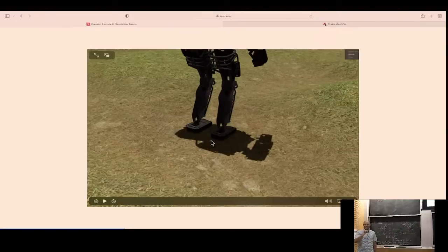It's the fingers. It turns out the way that we simulate the WSG, I guess I did say it maybe a little bit, but yeah, the WSG has a mechanical drive so that the two fingers are always equal and opposite magnitude. We simulate that with a stiff spring. Too stiff a spring. Like it has to be stiff, but it's the thing that drives the bottleneck of my simulator. That's annoying. Okay, but at least I know it. I found it, and I know that if I want to make my simulator faster, I can change that number or handle that stiffness properly.